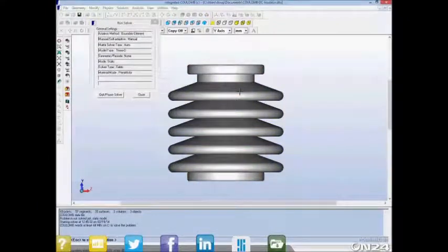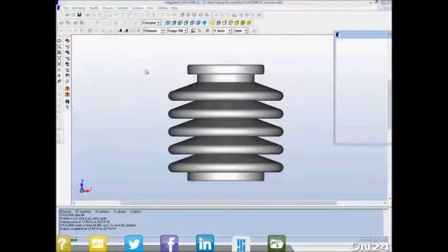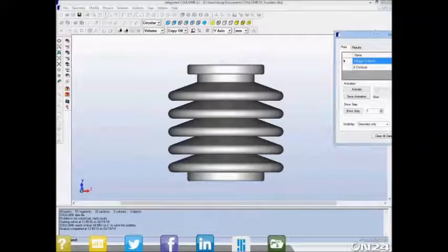and right now you can see that a boundary element solver is being used because I'm just doing a static solution. We generally consider the boundary elements to be better for that. We're doing a static solution but in permittivity mode. That means that the solution we see is going to be the voltages and the fields that you would get immediately after you flip the switch, that is, turn on however much voltage you've applied.